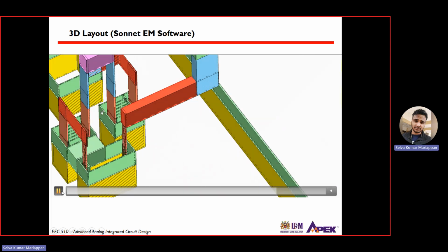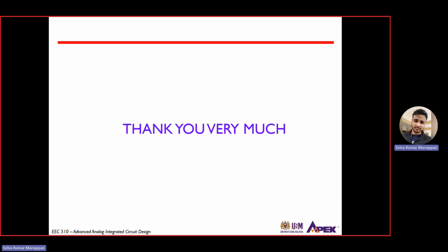Okay, so here, for example, this is my metal 1 and metal 1. This is my gate and source, but I cannot pull them because I have this bulk here. I cannot pull metal 1 and metal 1 directly here because I will short them. So instead of shorting them, I take from metal 1, go up to metal 3, and from metal 3 I go back down here. I avoid shorting this net. Go up, do a bridge, and then connect them back. So this is just a visualization for you guys.